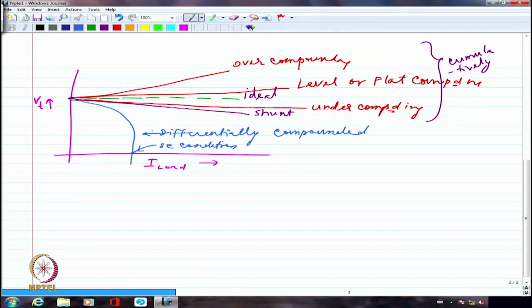So in the case of short circuit condition, where I want to limit the current still, and short circuit means voltage is 0, obviously. So this really comes in handy because I don't have to put any special control for making sure that the current does not exceed a particular set limit. I don't have to do anything.